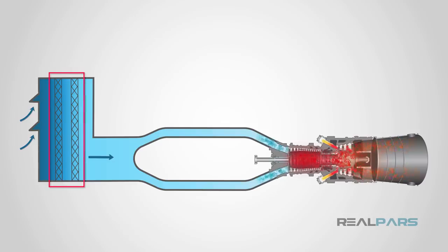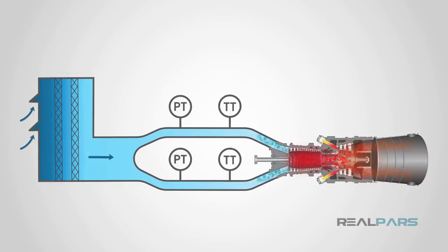The screening and filtration are basic requirements for incoming air. Also, proper instrumentation is mounted on the air duct to monitor the draft pressure and temperature. In harsh environments, the air might need to be preheated or conditioned. Also, differential pressure monitoring of air filters will warn the turbine operator of filter clogging.